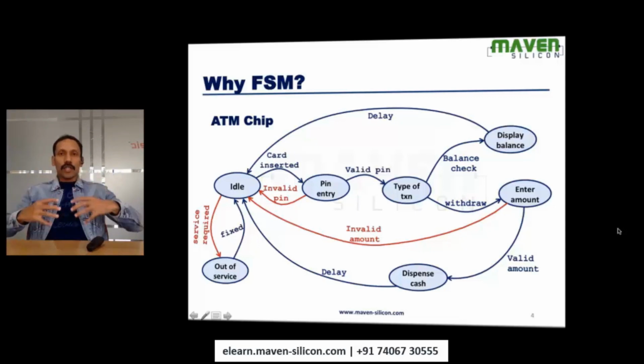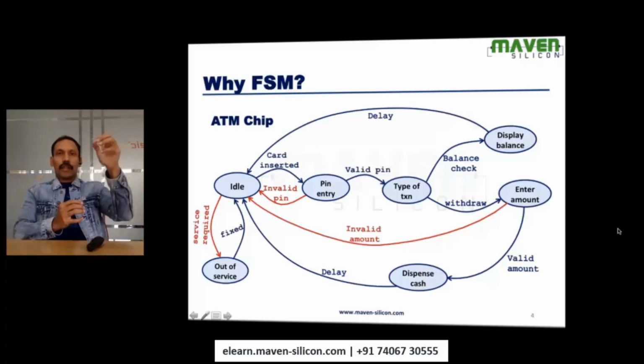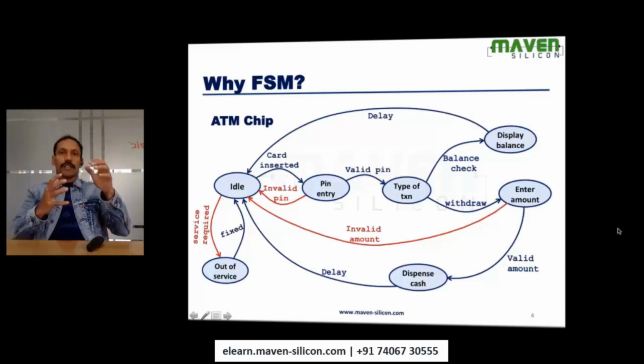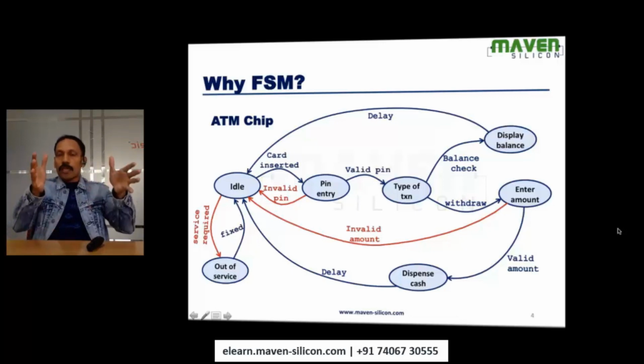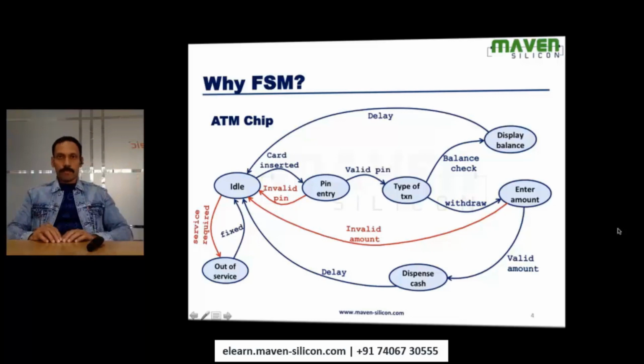Now what happens is, we write the source code and then we use a synthesizer to generate the logic circuit. So producing the logic circuit is completely automated with the help of the synthesizer. The synthesizer is going to compile your source code, and then based on the definition, based on the number of states you define, automatically it is going to produce the logic circuit. So finally you will come to know how many gates you really need to implement this particular chip. So the whole process is automated. The minimum thing that you need to understand is how to design this kind of FSM.